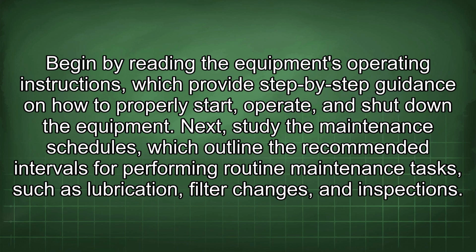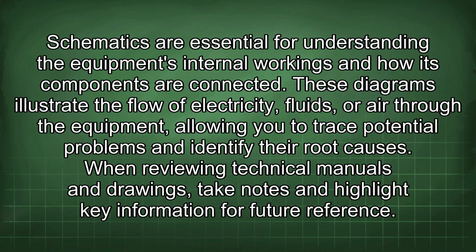filter changes, and inspections. Schematics are essential for understanding the equipment's internal workings and how its components are connected. These diagrams illustrate the flow of electricity, fluids, or air through the equipment, allowing you to trace potential problems and identify their root causes. When reviewing technical manuals and drawings, take notes and highlight key information for future reference.